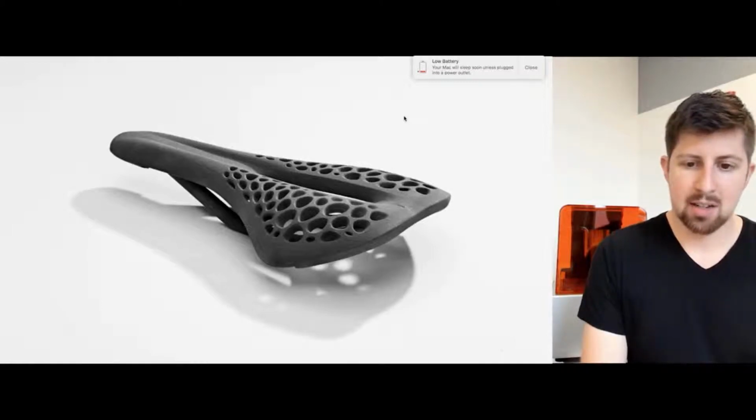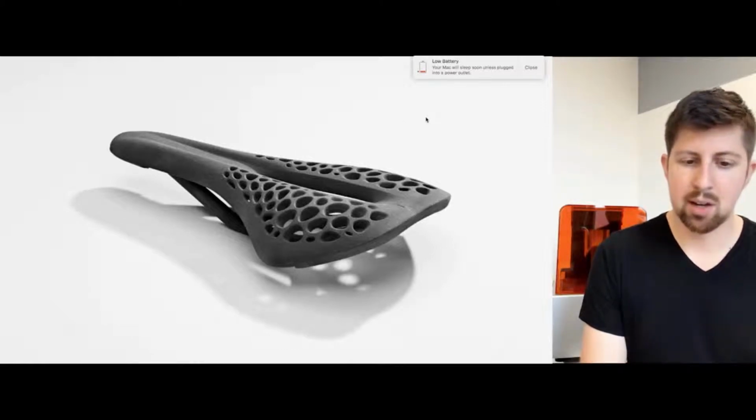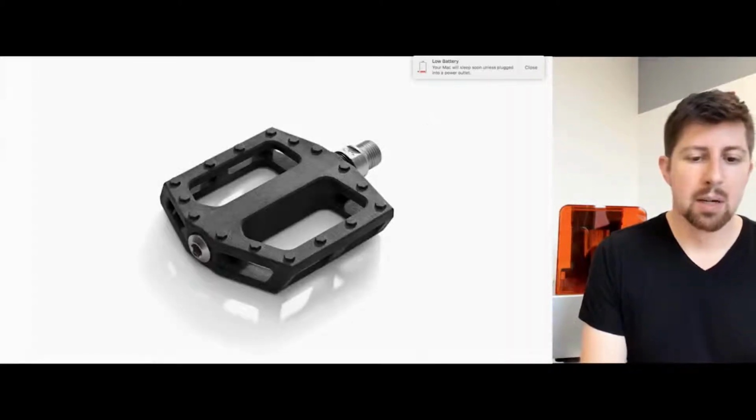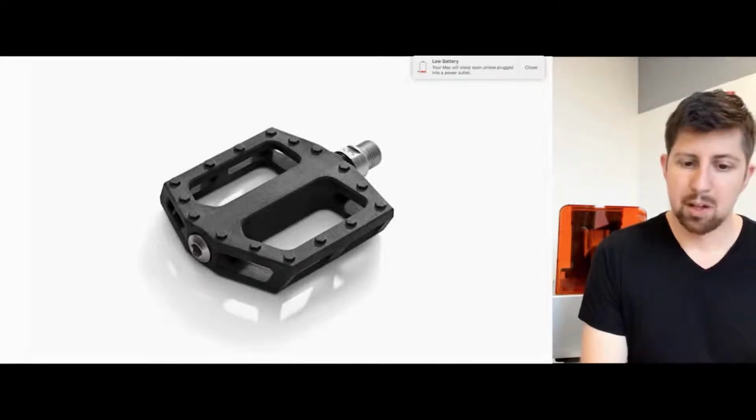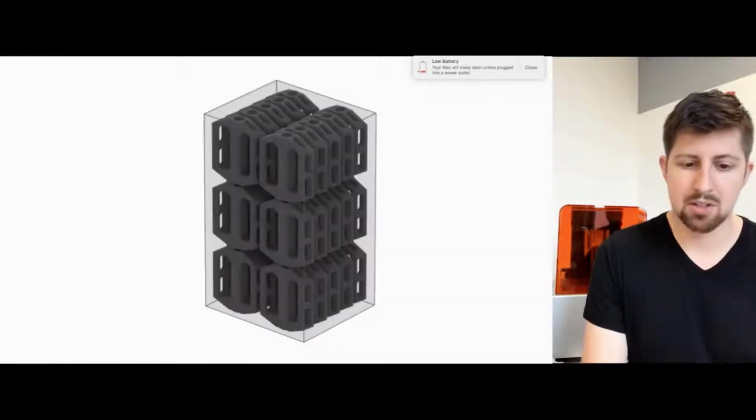And the great thing about that is it's a self-supporting structure. So you have printed parts that are self-supporting, which gives you more geometric freedom. And in this case, you're printing with polyamide, or polyamide 12, or nylon, so it's a really tough, resilient thermoplastic, which makes it useful for a lot of different applications that undergo a lot of stress and strain.